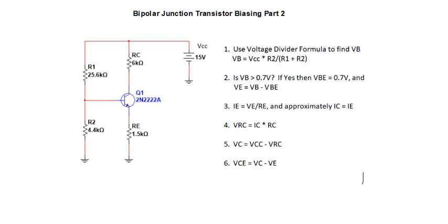Then we've got pin to ground voltages, VB, VC, VE, and pin to pin voltages, VBE and VCE. There is also a VCB I didn't list here because normally we're not very concerned with that voltage. As long as VCC is bigger than the base voltage, then we're not really that worried about it. But we'll go ahead and add that one on and find it also as we go through this.